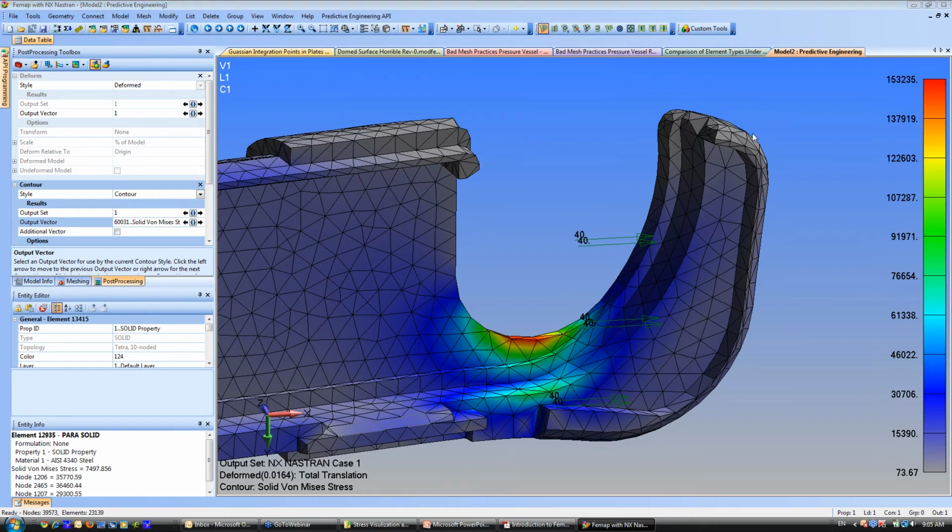What was really going on is that this thing, the 40-pound load, was something being done in quality control. They wanted this after it was made by powder metallurgy. After it comes out of the oven, they wanted to make sure it wouldn't break in use. And so someone had decided that, well, we want to use 40 pounds as the ultimate load, and if it survives that 40-pound load, we can go ahead and sterilize it and ship it to the surgeon. Well, what they were doing, they were pre-cracking these things. They would break them occasionally at 40 pounds, but the rest survived. They actually were pre-cracking them, and of course it would go to the surgeon, and as soon as he hits it with a stapling load, this tip would break off inside the patient.